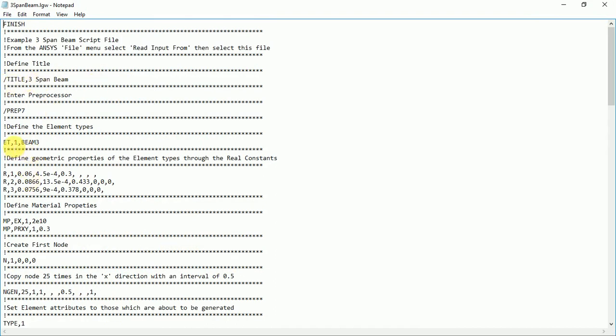So if I want to know about the element type, I just type in ET, comma, ET, then have a look on the help file, and it tells you what follows in sequence in terms of the comma delimited numbers or items that follow. Okay? Again, like the real constants, if you type in the R command, it'll tell you what sequence of R commands you should use. That tends to be element specific, so you'd need to look at the element as well.